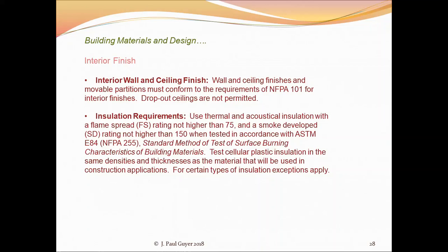And so the impaired patients are moved into this area of refuge, and the fire doors are closed, and they are in a protected environment while the fire is being extinguished. And of course, this also gets them out of the way of the firefighters so that the firefighters can do what they need to do.